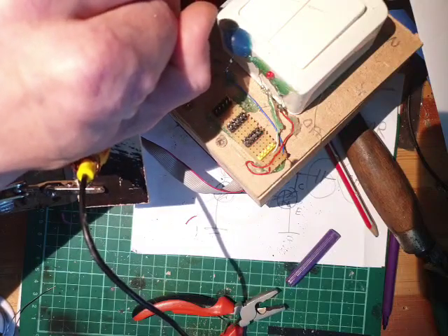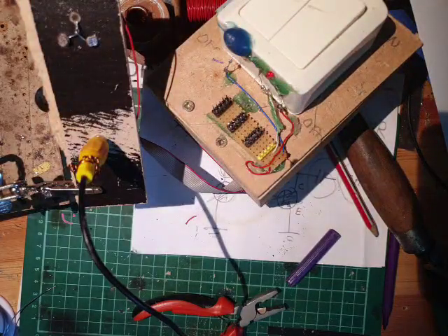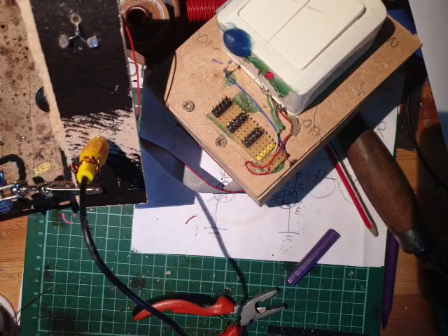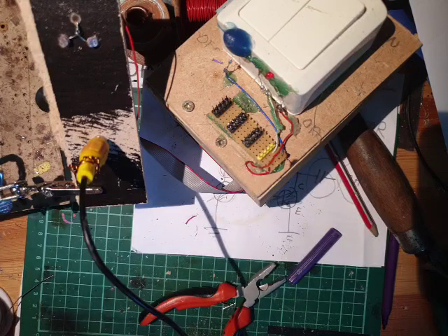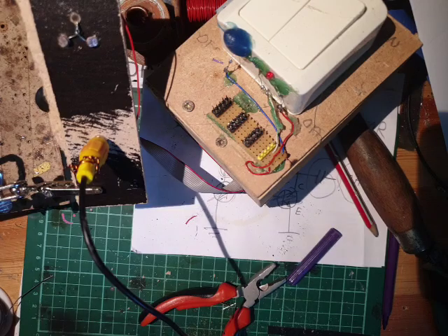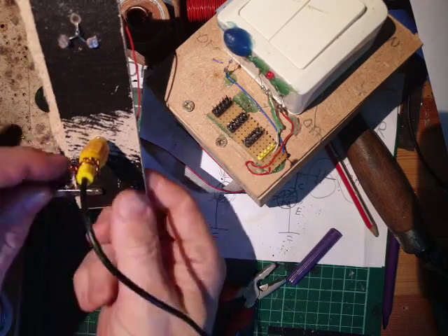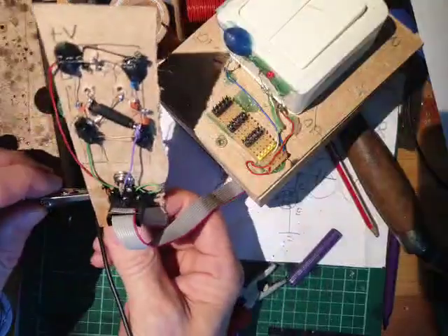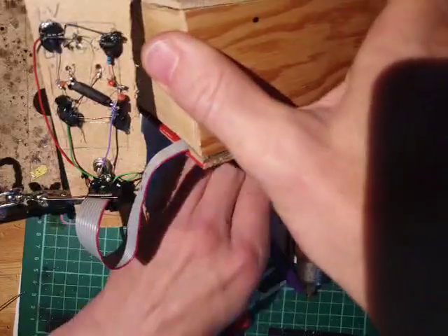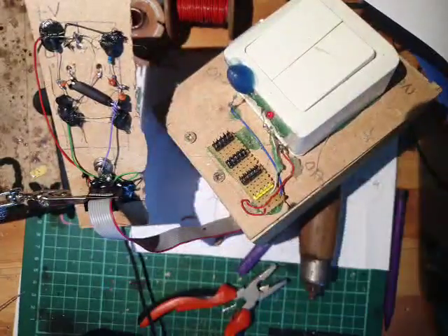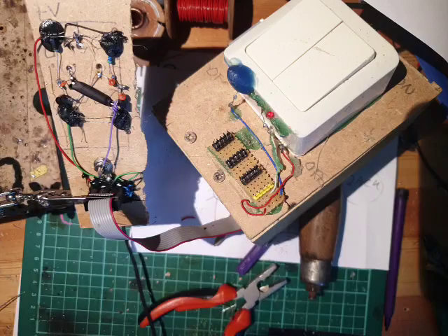So what does that mean? Well, it could be one of 2 things. Either we have a supersonic sound, meaning we can't hear it, maybe bats can hear it, and the other could be that there is no oscillation going on. So you could test with an oscilloscope, or you could just test with sort of manually pushing 2 larger capacitors against the existing capacitors like this.